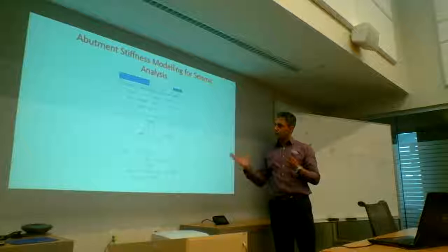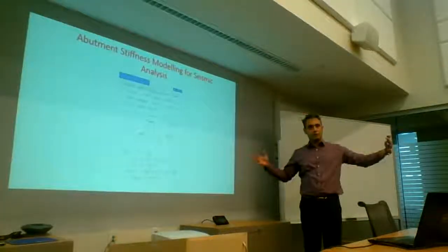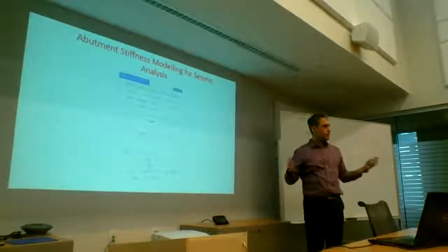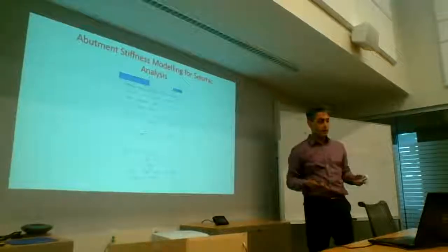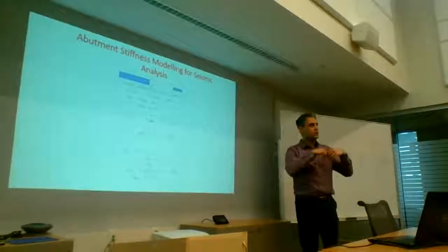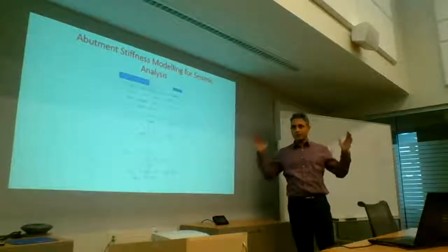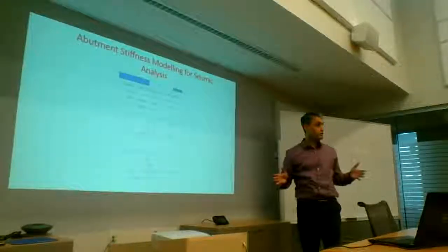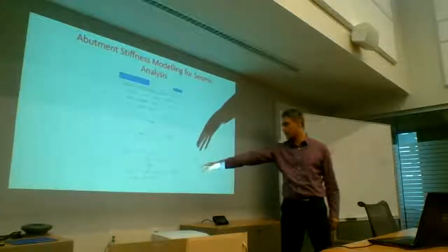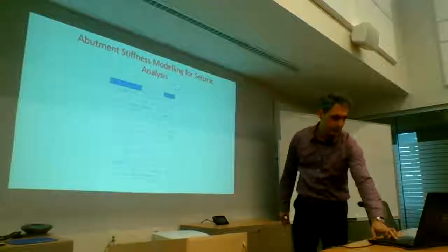You have to balance that against temperature and all that, because if your bridge is very, very long and it's jointless, when it expands and contracts, you're going to put in a lot of lock-in stresses. You've got to be mindful of that when you start locking everything in. It's a good idea generally, but the thought has to go a little bit beyond that. You can't just say, oh, I'm on a 200-meter bridge, I'm going to lock everything up, and then it could become problematic. So this is again just showing your first abutment stiffness is at 185,000 kilonewtons per meter.